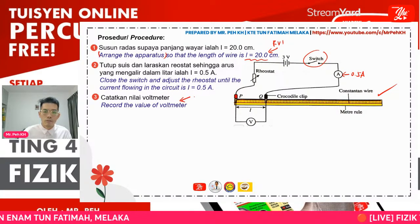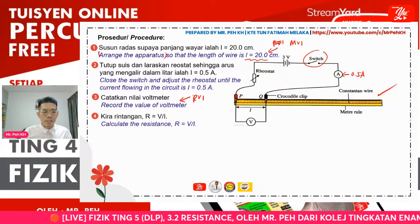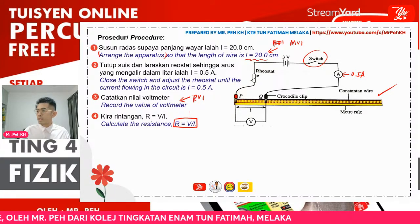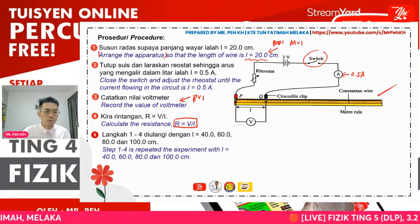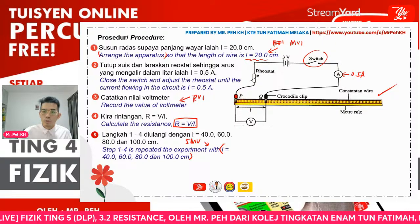This is your first MV, and this will be the first RV. Then calculate your resistance value with the formula V over I, which I showed you just now. Then repeat steps 1 to 4, until you have 4 more with different lengths. So minimum 5 MV, including the first one.